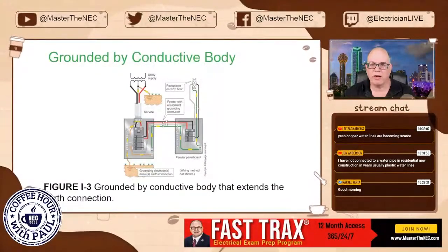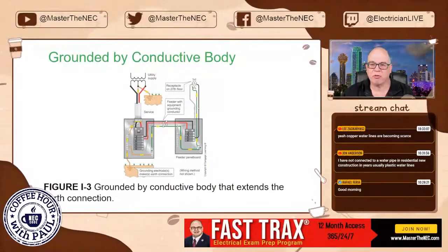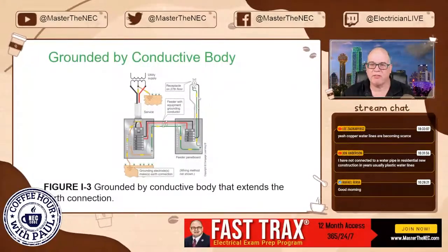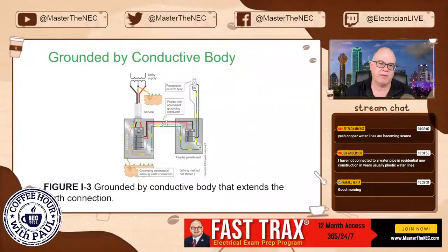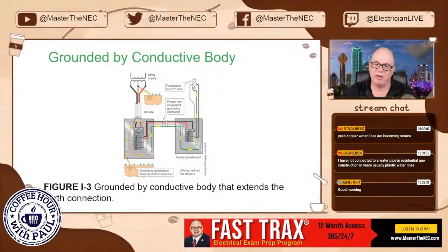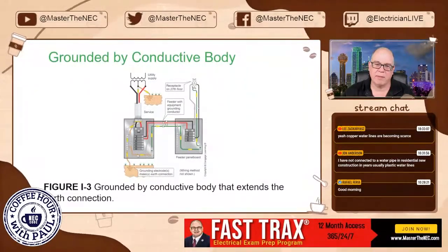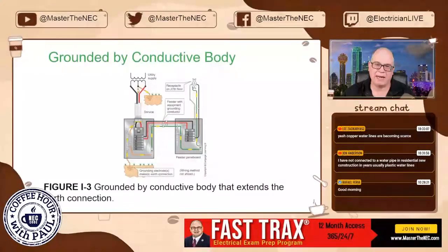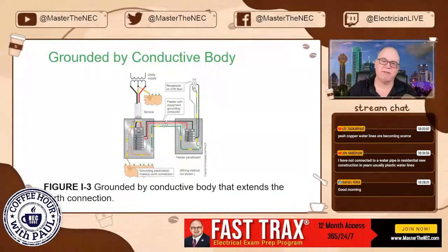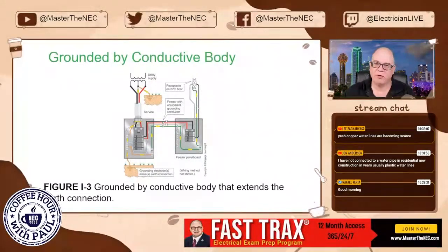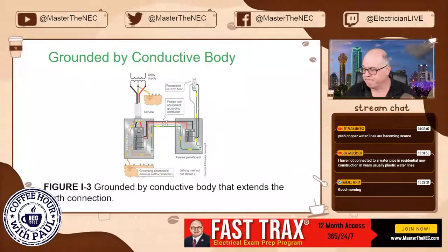So 4 conductors run out there, okay? And here you see that the actual equipment grounding conductor extends that path all the way up to the receptacle on the 27th floor. So there's your connection down through the bus, through that main bonding jumper, back over to the neutral, back to the source. That's what's going to allow the overcurrent protective device to clear if you have a fault down here at the receptacle location, okay?